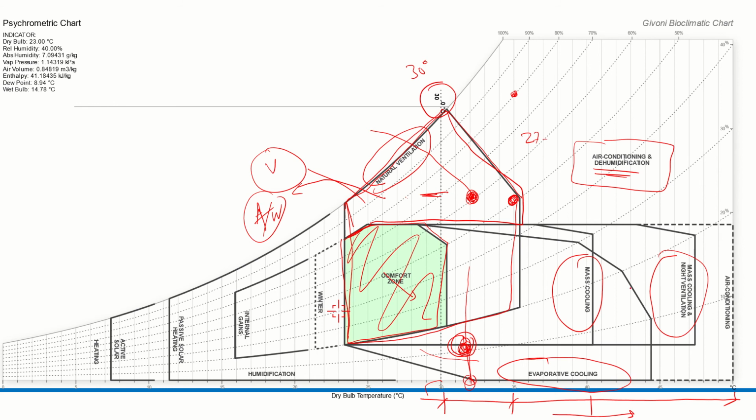Let's say this is actually done as one of the strategies that you must have also read and commonly said. Let's say you are somewhere here, 41 degrees Celsius, and humidity is very low. What do we say? Open up the windows so that night flushing. You must have come across this word, night flushing.